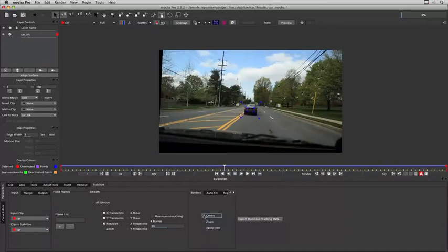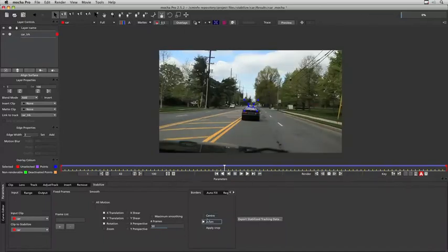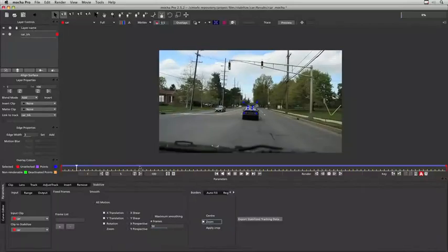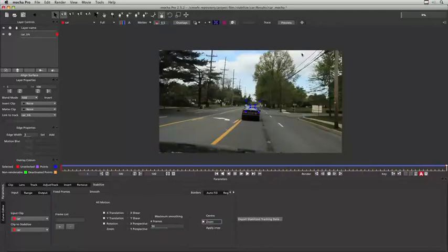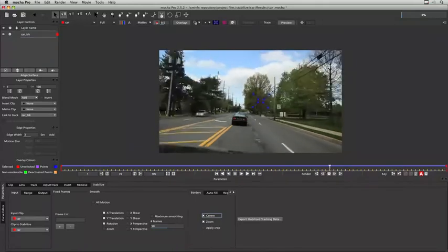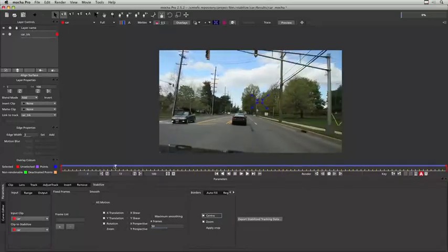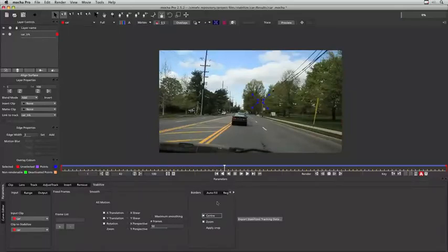The second option is the zoom, and the zoom will basically scale the image. It will remove all the missing areas from the frame, and it's the easiest option to use, but you will lose image quality because sometimes you may need to scale the image by 50% or so. Use it with care. And you can also use both options together and usually get a better result. It's a good combination to be used.